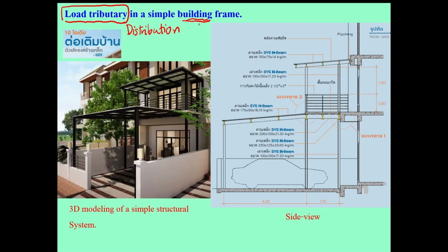The beam that is between column and column, that's the big beam. The big beam is the beam that connects column to the column. The beam that connects beam to the beam, or the beam between the others, we call small beam. Okay, the load will transfer from small beam to the big beam to the column. That's why we call it girder, because it connects column to column. But the one that just connects the beam to the beam, such as this one, you will call the beam.